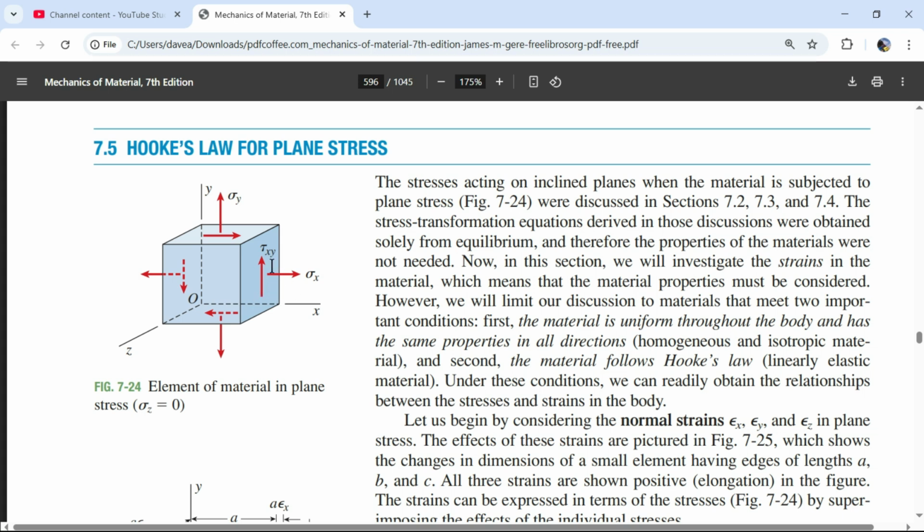and these stresses, this would be a stress diagram, but it is associated with a force diagram. So if I get down to this element, I can put this element down here and make a force diagram. This stress operates on this little chunk of area, and then that's going to be a force in that direction, and we're going to have an equal force in the other direction. There are no shear stresses and no normal stresses in the y. So when we incline our plane, that's when we start to slice through our cut, and then that is going to open up. We're going to have a force this way.